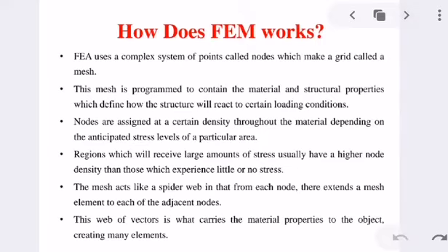Let's see how FEM works. FEM uses a complex system of points called nodes which make a grid called a mesh, and this mesh is programmed to contain material and structural properties which define how the structure will react to certain loading conditions.